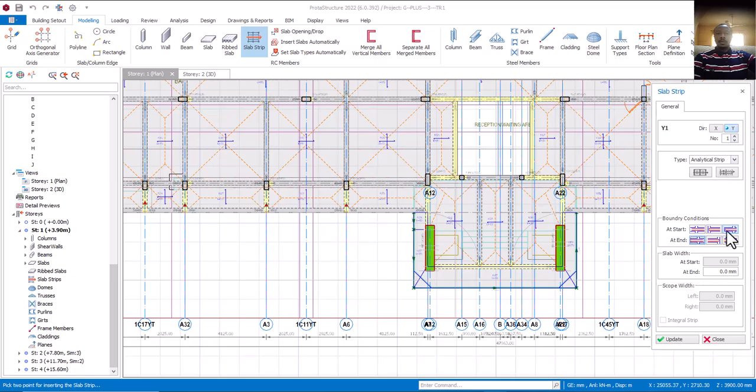So in this case now, let's say I'm using this one. Y is active. I can say okay, from slab to, for example, cantilever. From this slab, come down, press my control key and then click on this, and let's wait for it. So can you see it's not showing me reinforcement? I'll just press delete on my keyboard, not escape. Delete. I've deleted this one now.